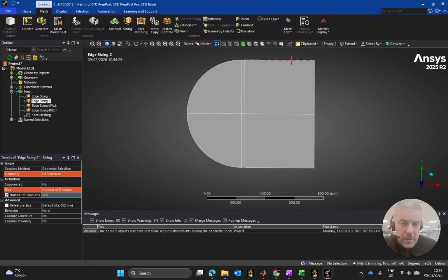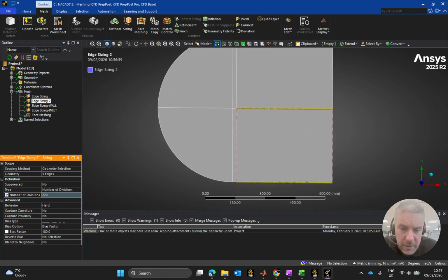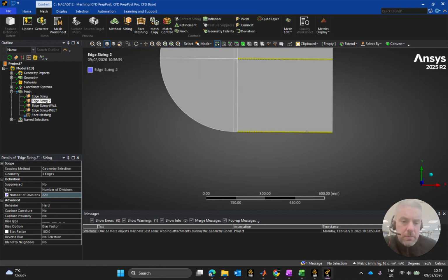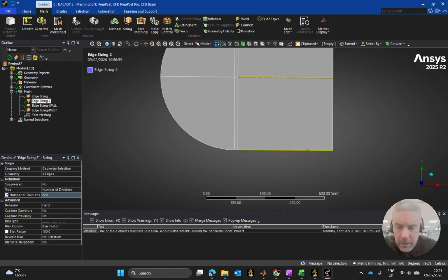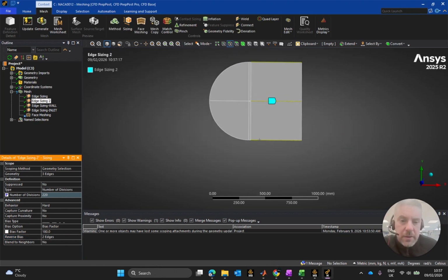Again, no selection. Aft was that, and that. That did have a bias, I believe. Apply that. So there's our bias factor. And we can see that the bias needs reversed on the bottom, this one here, and the middle. Alright, so I'm going to reverse bias. I'm going to select that one and select that one. Apply that reverse bias, and the graphic did stay with me this time.